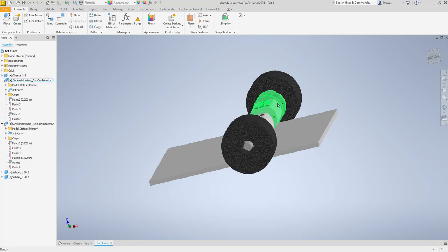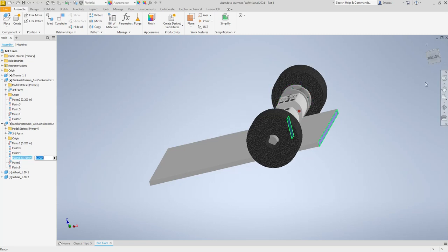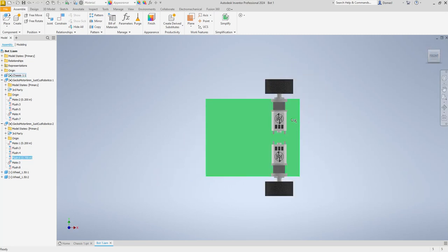So we're going to find the motor again and the constraint where I had the flush offset to the back right there, 1.5 inch. I'm going to say 0.75. I'm going to maybe look at a top view and make a judgment call here. If I put all my electronics up front and I have just this back here, I need to have a motor mount, that's probably pretty safe. I might be able to get away with 0.5 instead of 0.75. I'm going to go ahead and do that just out of curiosity. 0.5. I'm going to try 0.5. I may have to adjust that later, but I'm going to say that's where I want my motor to be. I'm going to save this assembly, and now we have that saved for what we're doing.